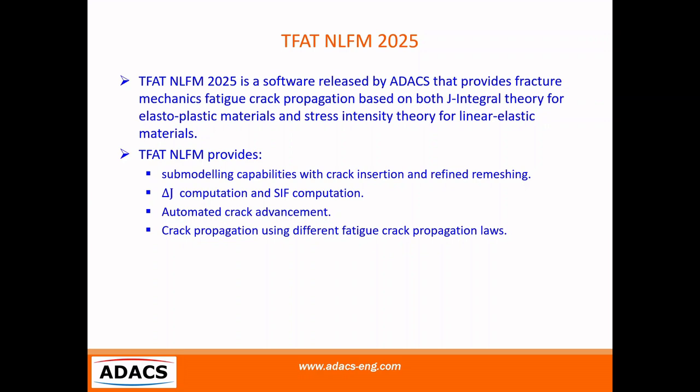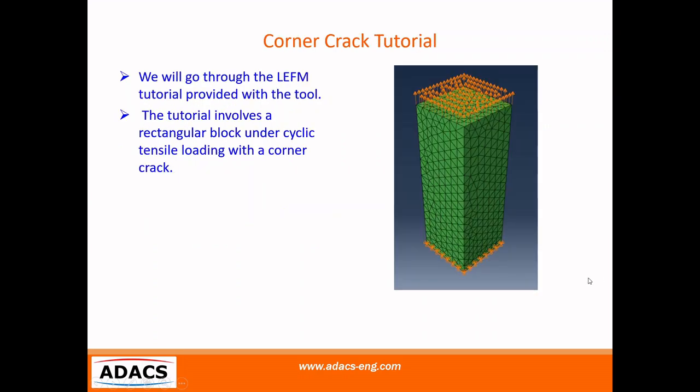TFAT NLFM also provides delta J computation and stress intensity factor computation along the crack. It provides automated crack advancement. Finally, it provides crack propagation using different fatigue crack propagation laws. So in this video, we will go through one of the tutorials that comes with the software, which is based on LEFM. The tutorial involves a rectangular block under cyclic tensile loading with a corner crack.